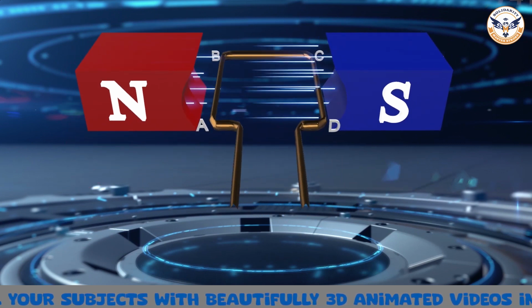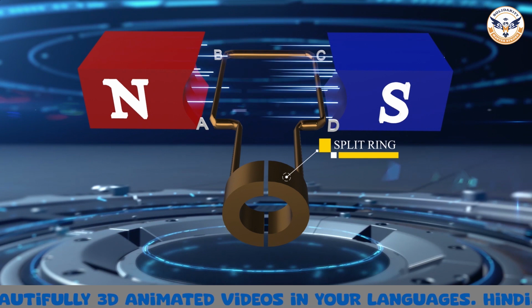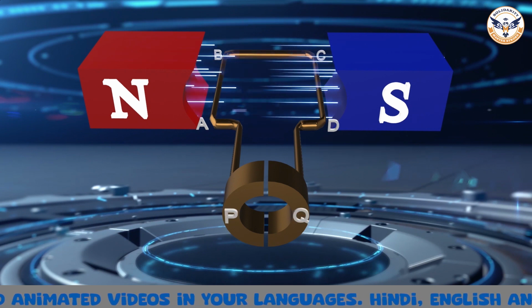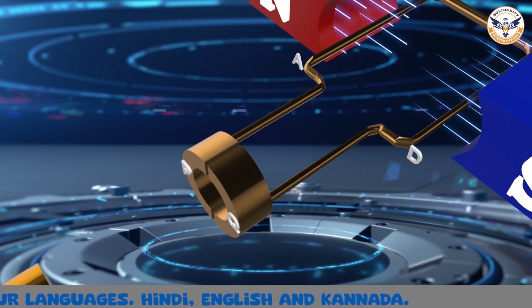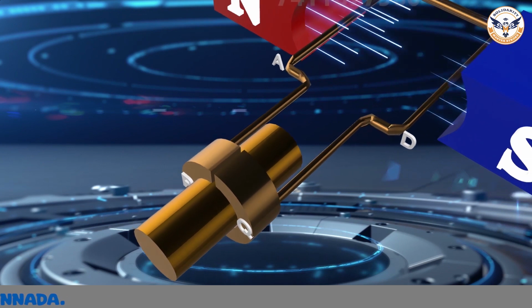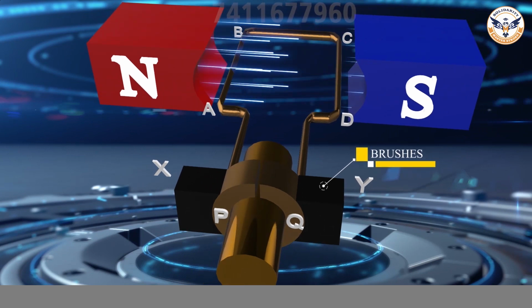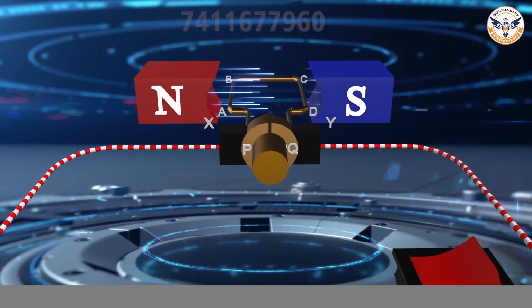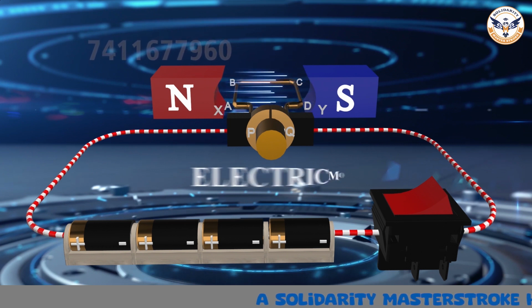The two ends of the coil are connected to the two halves of a split ring. Let's label them as P and Q. The inner sides of these halves are insulated and attached to the axle. The external conducting edges of P and Q touch the two conducting stationary brushes X and Y, and these stationary brushes are connected to a source called a battery. So, this is how the complete setup of a simple electric motor looks.